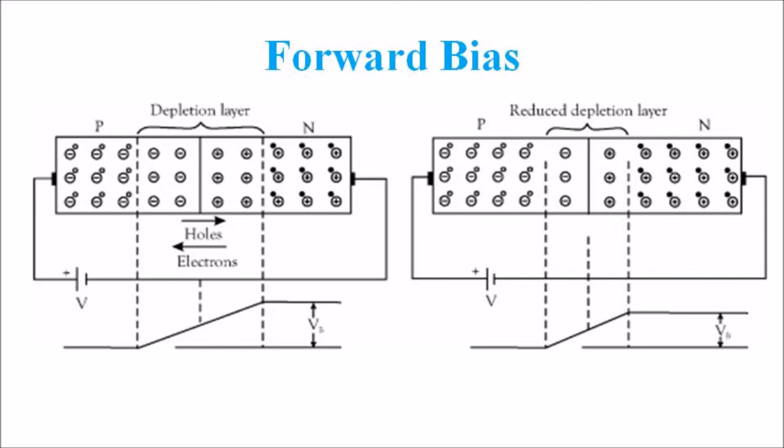Although the electron penetrates only a short distance into the p-type material before recombining, the electric current continues uninterrupted because the holes begin to flow in the opposite direction, replacing the ones that the minority carrier electrons recombine with. The total current is constant in space because any variation would cause charge to build up over time. So the flow of holes from the P region into the N region is exactly analogous to the flow of electrons from the N to P region.